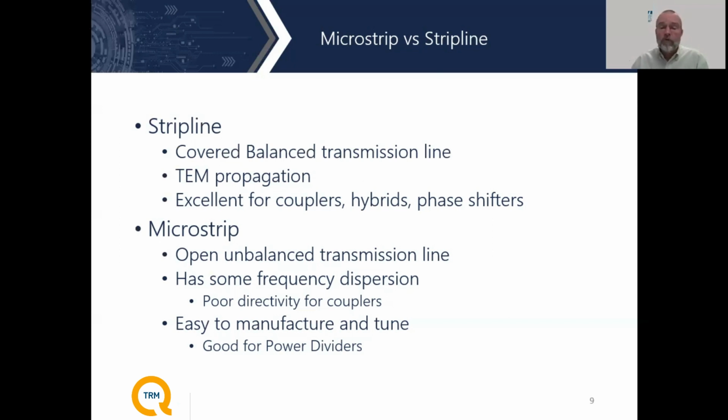Going through those sorts of devices, strip line becomes a necessary item in order to be able to build broadband directional couplers that have good directivity. It's just an important piece that sort of limits microstrip. Microstrip can be balanced over narrow band frequencies.